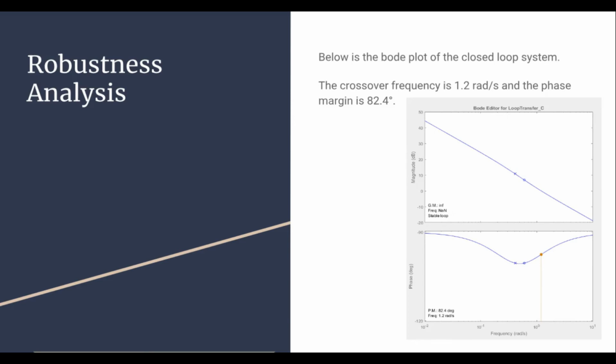There is no gain margin for our system, which we also saw on the root locus. This is because the phase margin never passes 180. The gain is only limited by the actuators we can get, and in general, increasing our gain will improve the response of our system in every way.